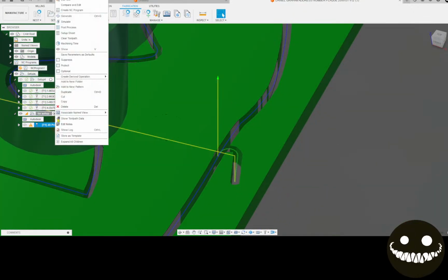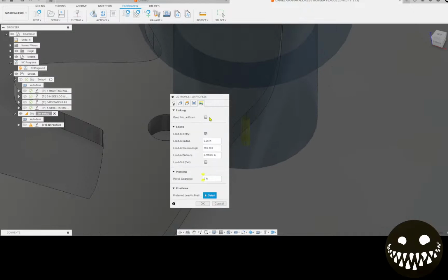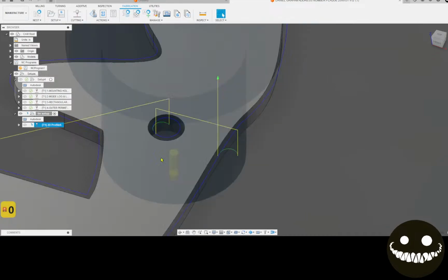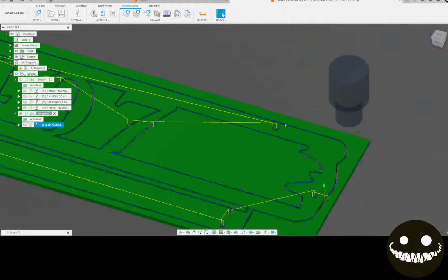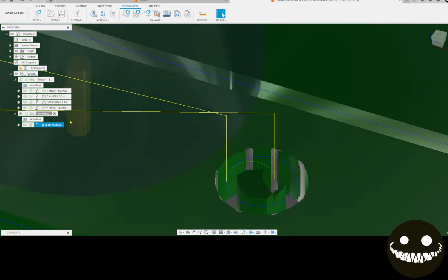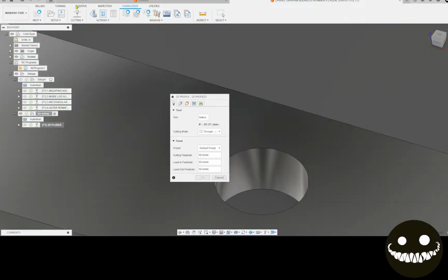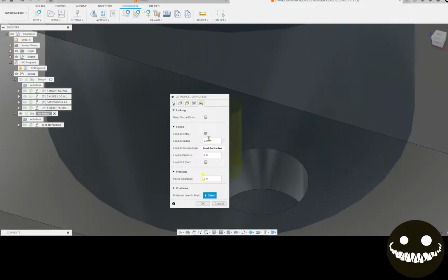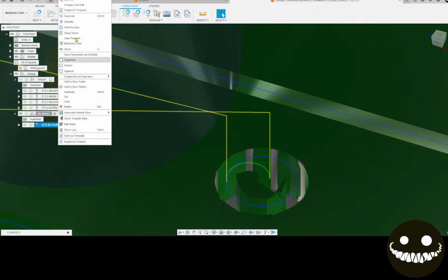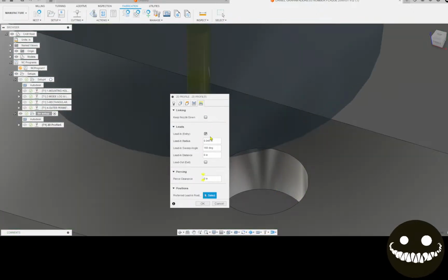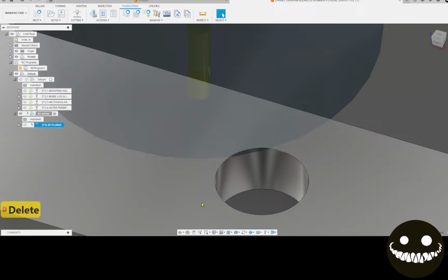Oh, pierce clearance. No, it's our, oh, this big lead-in distance of 0. Yeah, it's looking a lot better. Okay, generated everything that time. And we could probably go a little less on that. Those holes, edit. Let's do 0.45 instead. Ooh, even less. Edit. There we go.